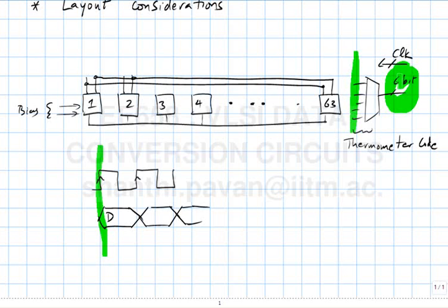Not only that, whenever there is a transition in any one of those 63 output lines, the transitions will all line up in time, correct? Because the transitions all occur at the same time, because the delay in all the logic gates is 0. In practice, all logic gates will have delay, and since some outputs pass through different types of gates inside, I would be very, very surprised if the output transitions at the decoder all line up in time. So with finite delay, there are going to be skews at the edges of the output of the decoder.